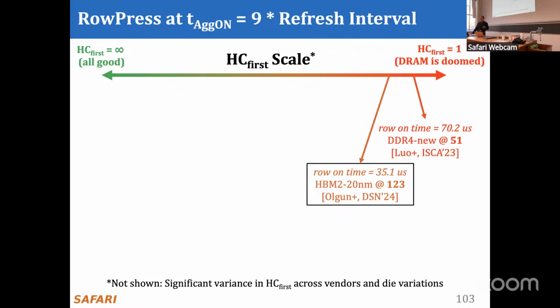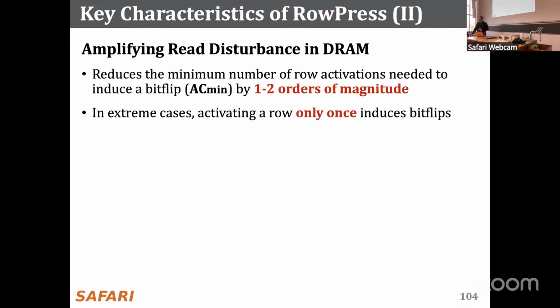The question is, of course, can you do this on a real system? On a real system, it's much harder. But before we go into the real system, in the paper, we have a lot of results that show that this is different from RowHammer, because row press gets worse as temperature increases. And again, we didn't know exactly why, but later works in the device level that got inspired from this work described why this happens as temperature increases, because it's really a leakage mechanism. It's called the passing gate effect, actually, in some of this literature.